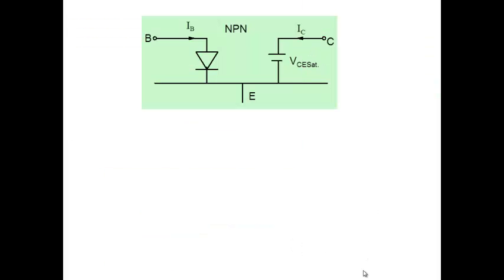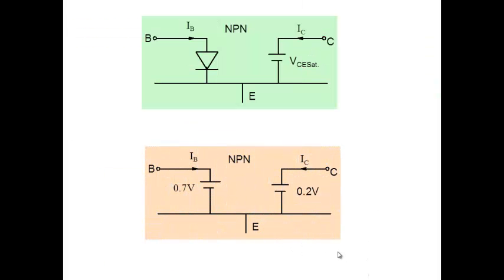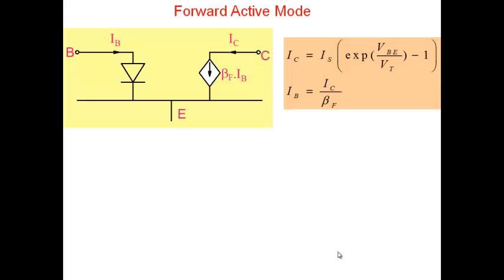So now we know that the transistor can operate in different modes: forward active, reverse active, and saturation. So these models are valid for the saturation region. So what I'm going to do is very quickly develop for you a generalized transistor model, a model which is applicable in forward active, in reverse active, in saturation region, any of those modes. Okay. Now to do that, let's start with the forward active mode first.